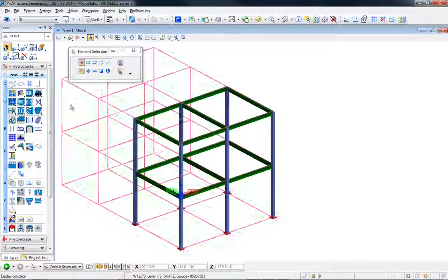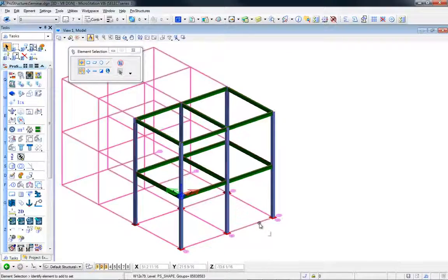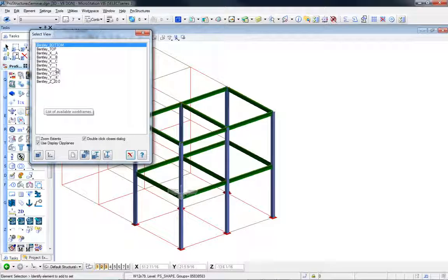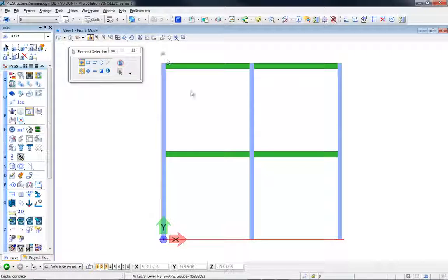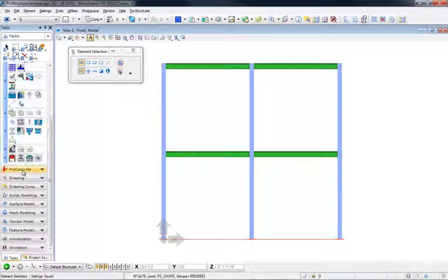Next step, I want to insert some bracings. We have this 3D grid here, and this is not only lines. What we have done here, we have created some views. So I want to go to the first view and say here in this area I want to insert a bracing. So these views will rotate to the correct view. It will set my ECS, UCS, so I'm working on the correct plane.